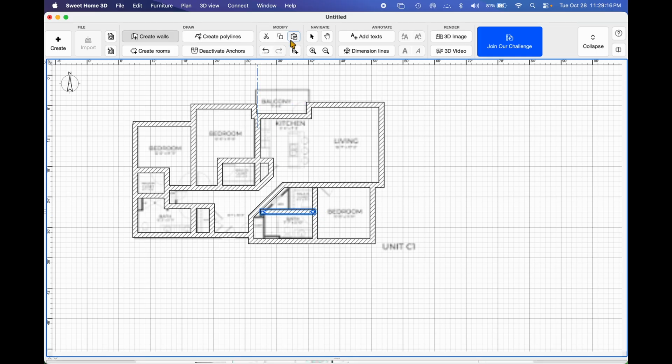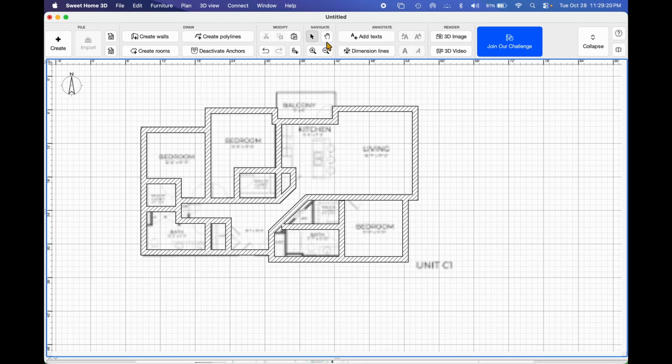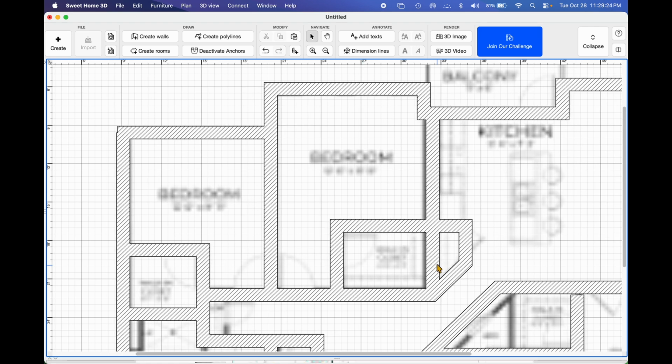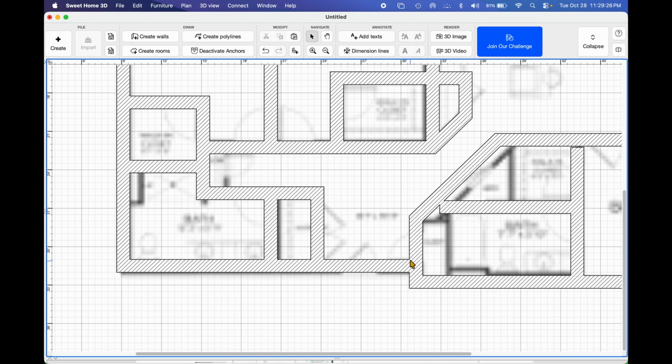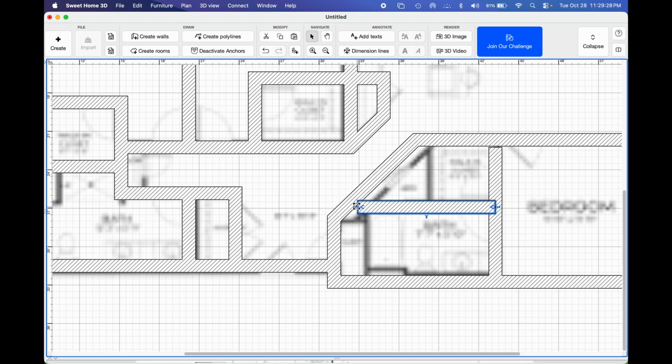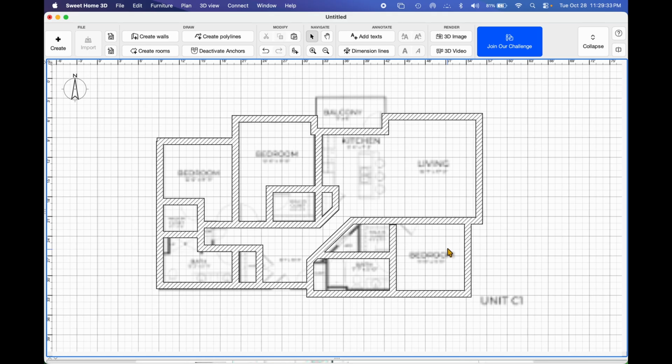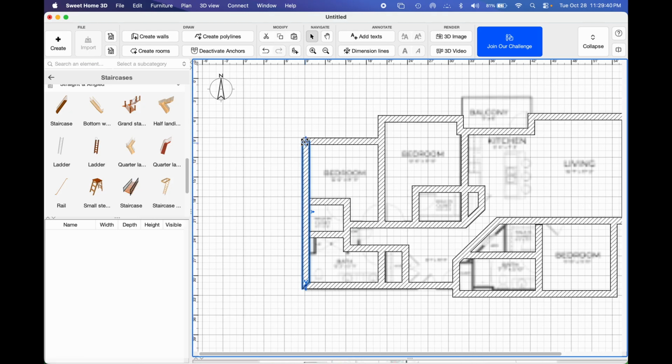Once you are done, you can adjust it a little bit. Click on the arrow or the pen icon. If you click on the pen, you can move it, and if you click on the arrow, you can use the shift button and your mouse cursor to move it. Also use the arrow keys to move it. Use Control and mouse cursor to zoom in and zoom out.